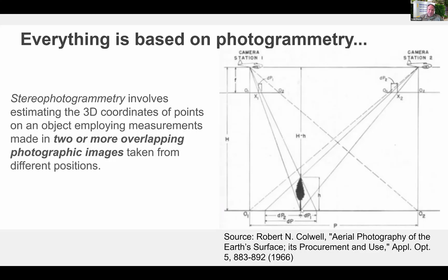So if you get the base of the tree and you get the angles, and then you tie that to the telemetry data, which by the way is written to each image that a drone takes. The drone has a GPS on it and other instrumentation. Sometimes it includes angle and so forth, but usually the main things are your altitude, your latitude and longitude. Each time a drone takes a photo, that information is written to what's called an EXIF file, which is paired.